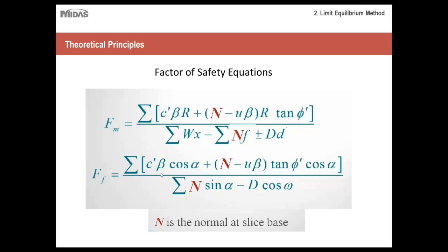And just as a recap, I'm sure you're all familiar with what the factor of safety is, but to reiterate, the factor of safety is essentially a ratio of the forces that are keeping the slope stable versus the forces that are acting against the slope, pushing against it to maybe cause it to fail. Usually a minimum factor of safety for most cases would be about 1.5. In other words, for every 1 Newton of force acting against the slope, causing it to be unstable, you'd have 1.5 Newtons of force acting against it to keep it stable. So the higher your factor of safety, the more stable your slope is.